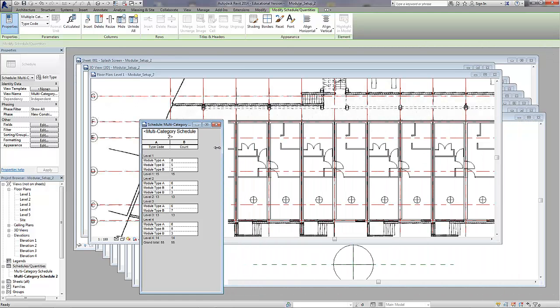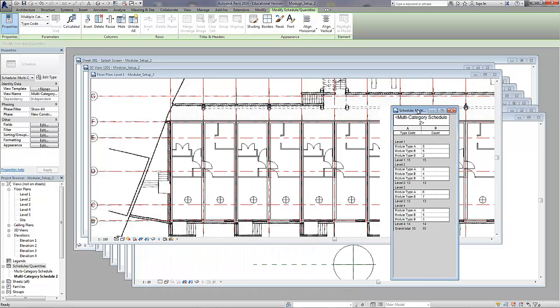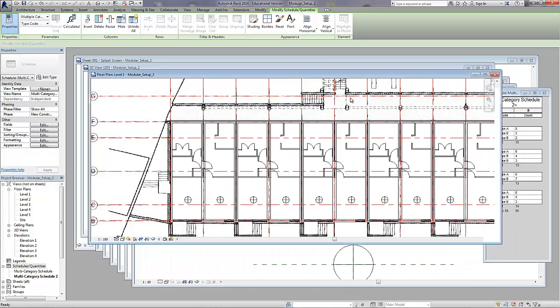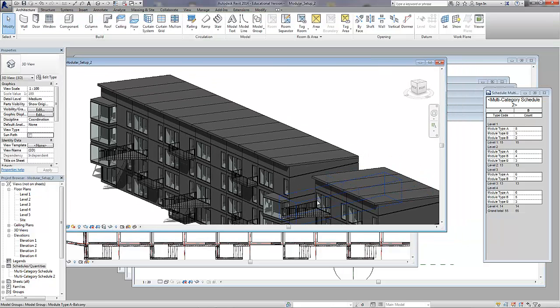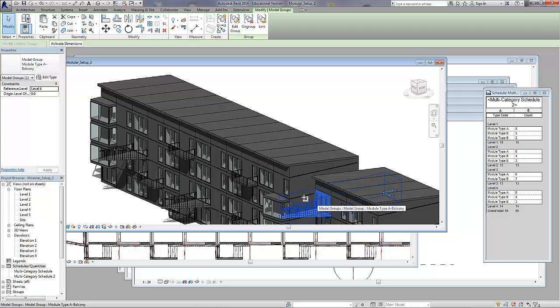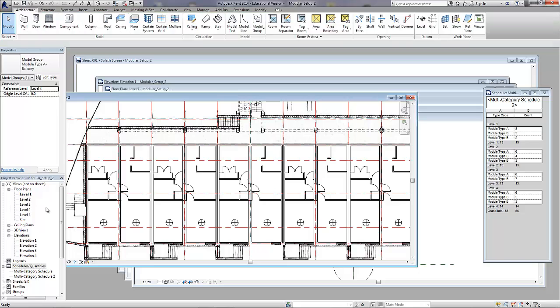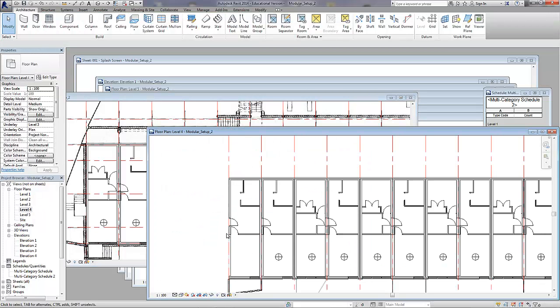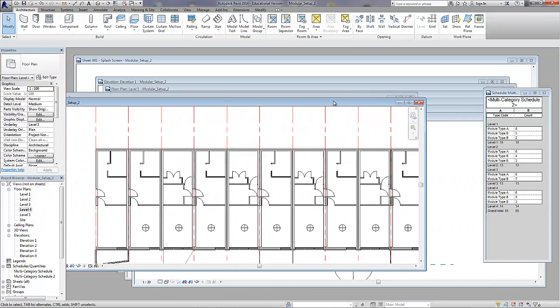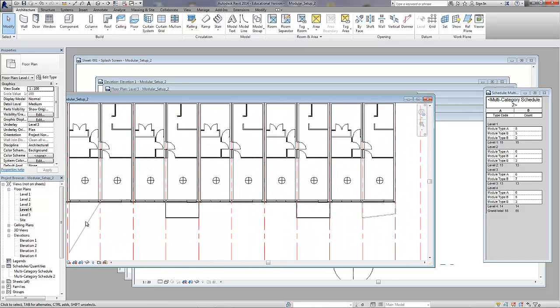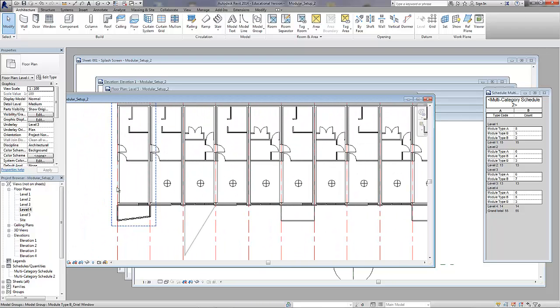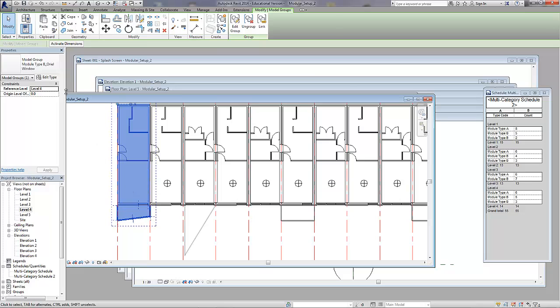and you can see that the levels act as the main dividers, and the module types are numbered according to level. So now, if we have a look at the overall model, we can see we've only listed the 3 module types we gave an identifier to, so we need to go and give an identifier to the other types of modules. I'm going to leave the schedule on the screen just so you can see how the schedule will automatically update as we add the identifier.